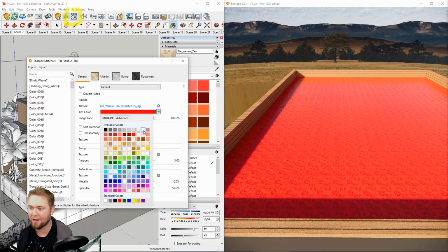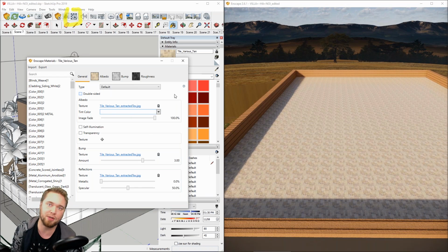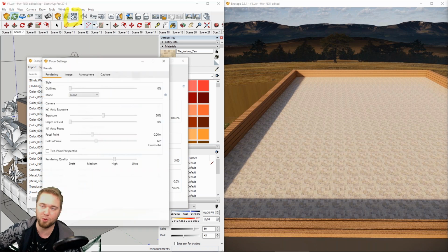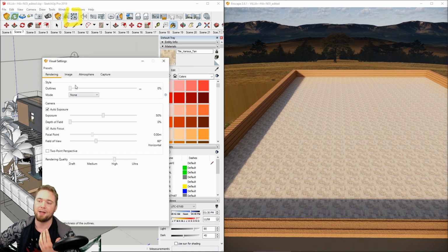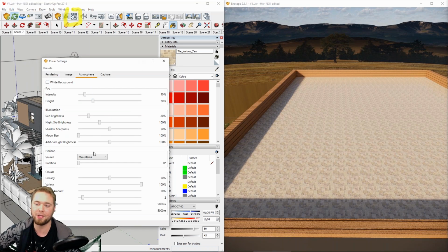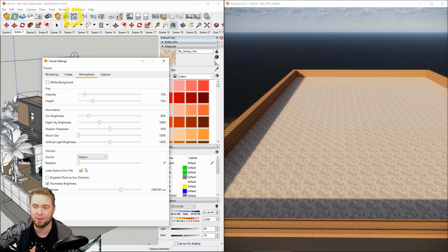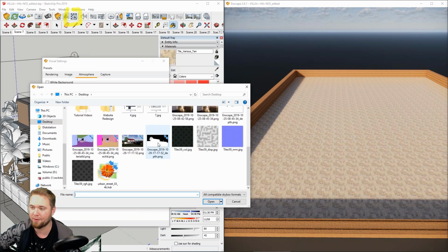We have changed a little bit about our settings arrangement or our settings windows, but that didn't have anything to do with our materials, so they shouldn't be touched by that at all. And if you say some parameters do not seem to register as HDRI rotations, for example, well, with HDRI, you are referring to a skybox. Useful note on the side here, Enscape does not only need HDRIs. It will work with any type of image file.